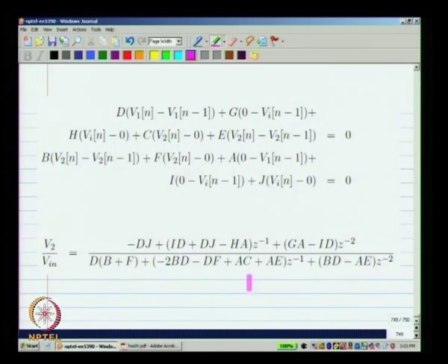Again, I leave it as an exercise to you to transform a band pass filter into its discrete time counterparts and compute the values. Okay. Now, usually it turns out that, to start off with, because there are too many degrees of freedom, you set B and D to be 1. Obviously, we do not mean 1 farad here, it is a unit capacitor whose absolute size you can choose later. Okay. B and D to be 1,